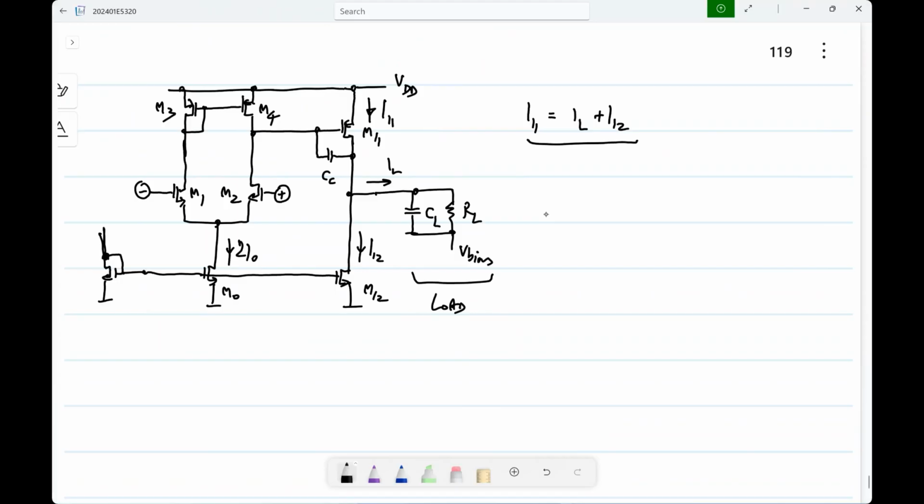Okay. Almost every circuit is like this. The same goes for RF power amplifiers in your mobile phones and so on. It's not that it is always in the transmit mode blasting the maximum power. So a fraction of the time it will be either idle or transmitting very little power. I mean, basically delivering a small IL. So basically this leads to power inefficiency, right? You are wasting power when it's not required. So if you had an architecture where you have a small quiescent current, but you can deliver a large load current, that would be better.